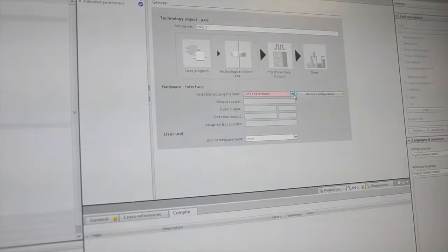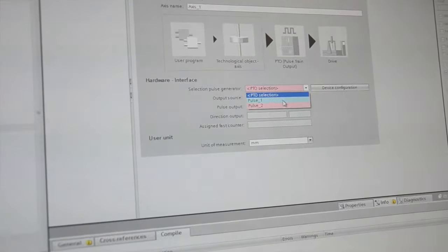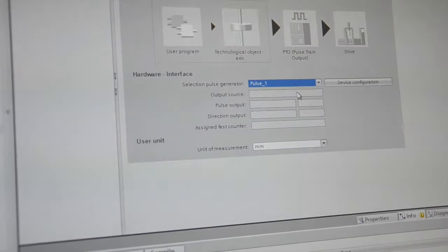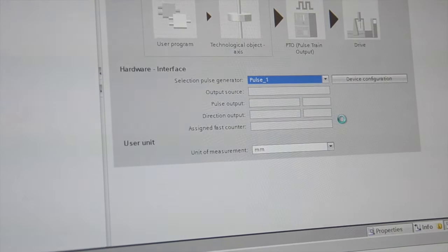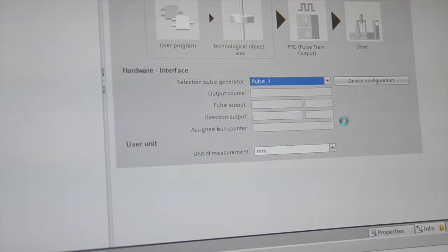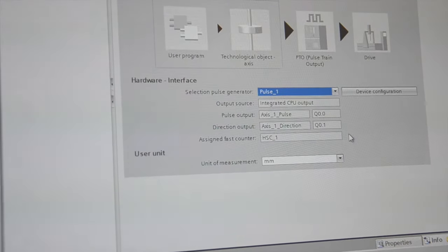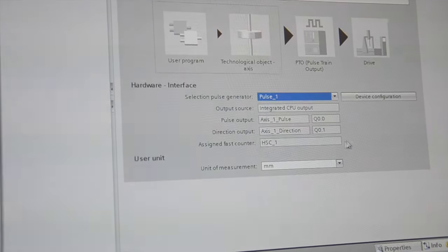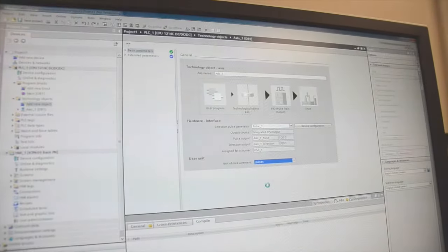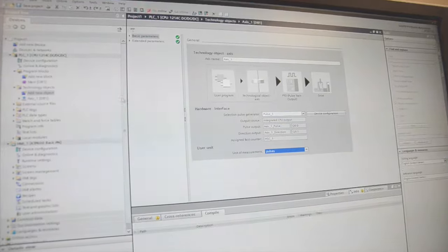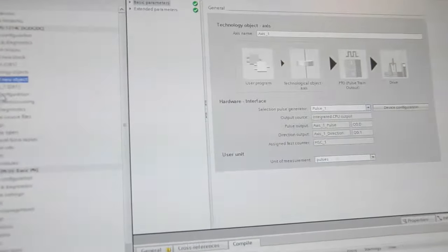After that, we will define the mechanical parameters of the machine. First, we will define steps per revolution, then distance per motor revolution, and then invert direction signal. After this, we will set it so hardware limits are not enabled.